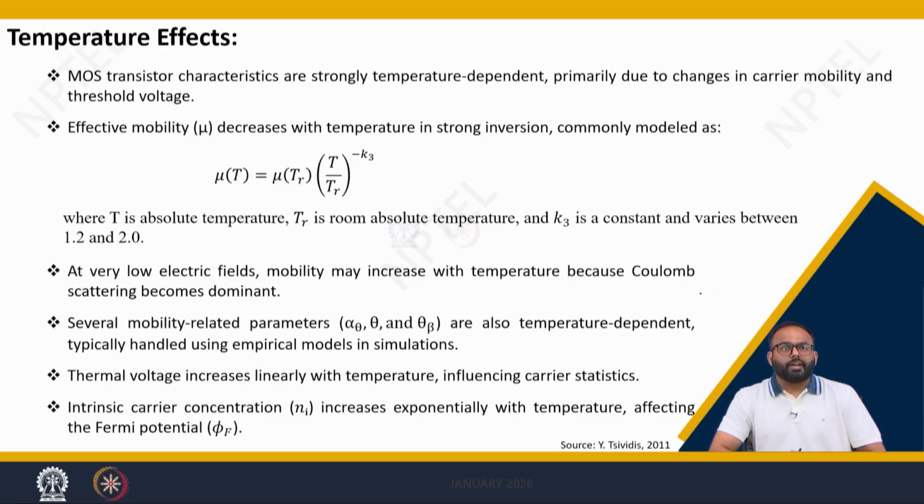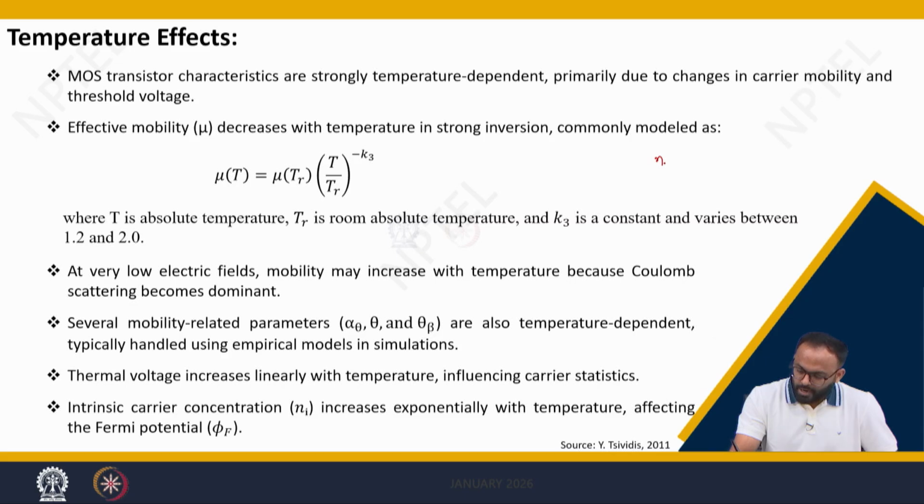Let us see another effect which affects the performance of your MOSFET or, in general, semiconductor based devices. We can simply say temperature is a very crucial parameter which captures all of your important parameters related to the semiconductor. For example, the well known parameters are the intrinsic carrier concentration, ni, which is dependent on temperature. It is approximately proportional to T to the power of 3 by 2.